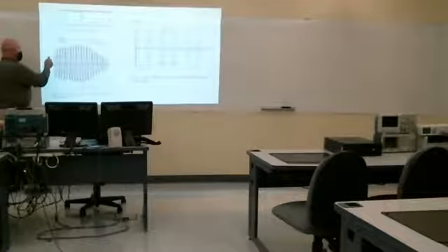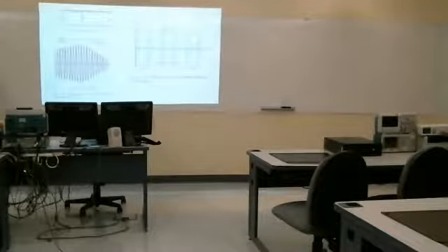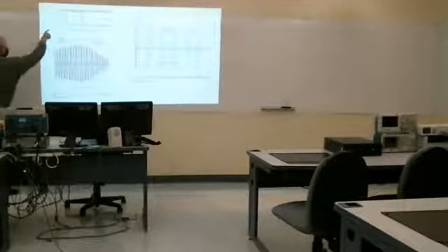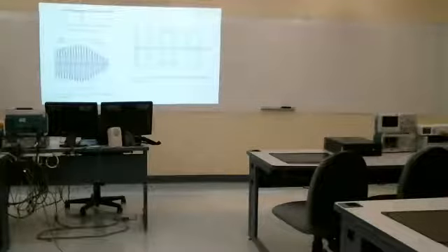So if you remember a half-wave rectifier, they're typically with a sine wave coming in. You run it through the diode, which with a half-wave rectifier removes the negative portion of the sine wave, and then the capacitor follows the humps.